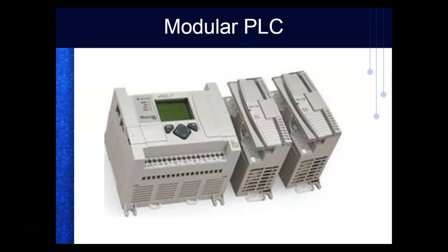This is the type of PLC that's become very, very popular. They still refer to this as a modular PLC. I call it a hybrid PLC. So this is the actual 1100. So this is MicroLogix 1100. And then it's got a panel on the side that you can snap off and you can add multiple modules. So the backplane actually runs through the microprocessor and through the module. Everybody understand that? Makes sense?